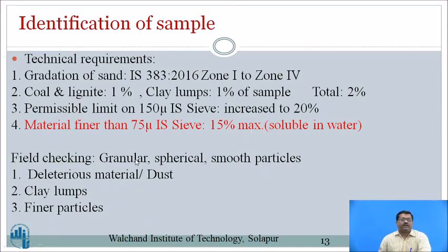Field check: the crushed sand shall be granular, with spherical, smooth particles. Deleterious material shall be very low, dust shall be very low, clay lumps shall be very low, and fine particles shall be restricted to 15%.